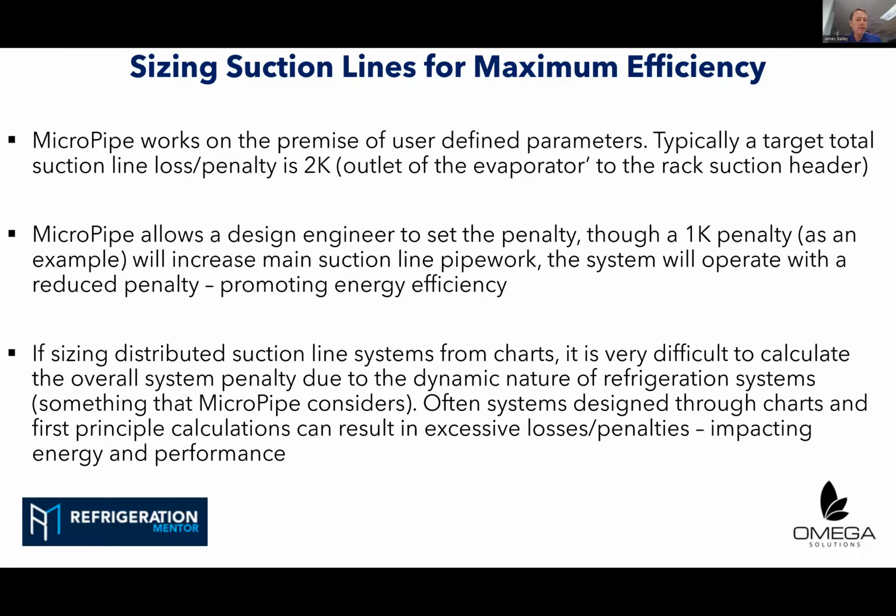And yes, you need that perfect storm to actually ignite the refrigerant. We're still constrained by volume, and we work to a volume of 54 kilograms within a system. To ensure that we wouldn't exceed the total volume, in the liquid line we tightened up the suction line, or rather, we expanded. So we let go a little bit of efficiency to get smaller pipe working, so we mitigated and met the criteria as laid out by what we follow in the UK.